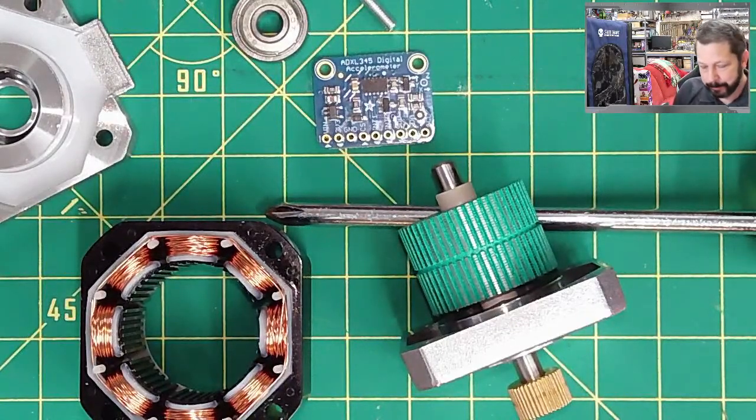It's sort of like a very fast version of what the BL Touch does, where the BL Touch knows the bed is misshapen somehow, and it moves the Z-axis up and down to accommodate for that. Input shaping does the same thing, except that nothing's deformed. It just knows that if it tells the print head to move in a straight line and the print bed is shaking, that line is going to have oscillations in it. So it says, instead of printing a straight line, print basically the opposite of the oscillations that the bed is going to experience, so that it ends up a straight line in your part.